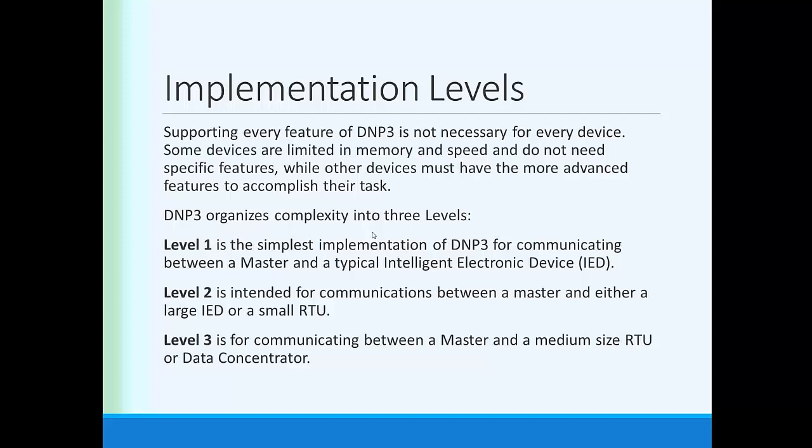The DNP protocol doesn't really give an awful lot of distinction between what has to be a level 1 device and what has to be a level 2 device. There are a number of optional functions. So you can have a level 1 device that supports a number of functions in level 2, but doesn't support all of the level 2 functions, and it may be perfectly usable in a SCADA system.